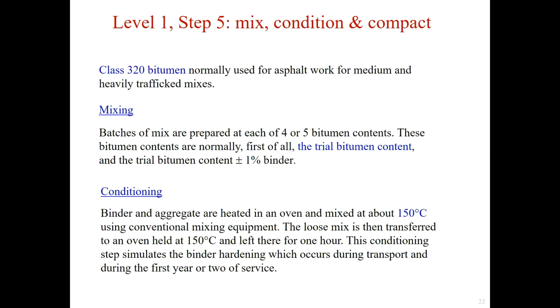As I discussed before, the class 320 bitumen is commonly used in asphalt for medium and heavily trafficked mixes, so we will choose it for mixing. The mixing is conducted for a range of bitumen contents and normally in between 4% and 6%.